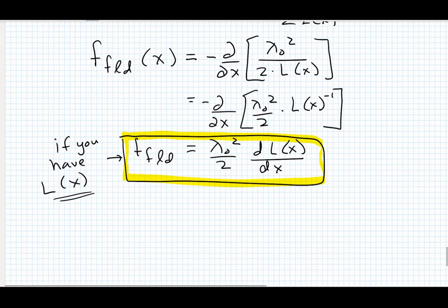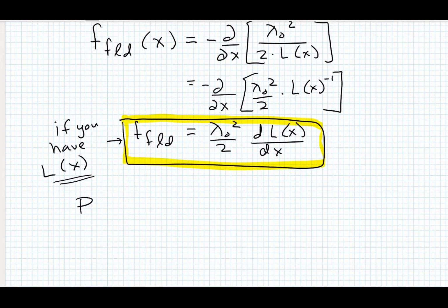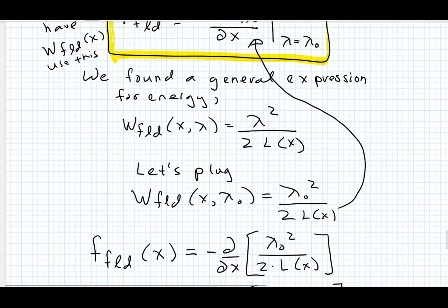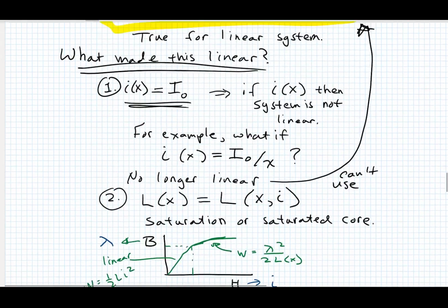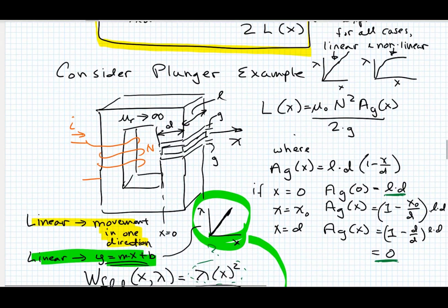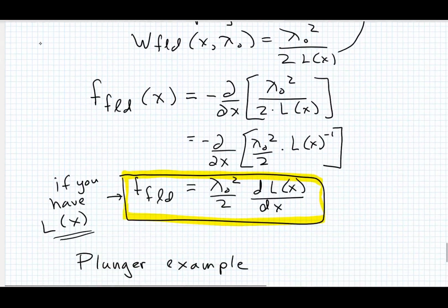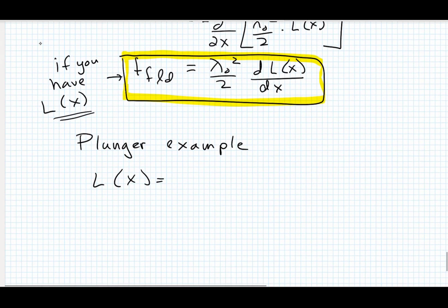So if we go back to our plunger example, we have an L of x in that example, right? It was this expression right here. So let's just use that, take the derivative of that, and we can find the force.